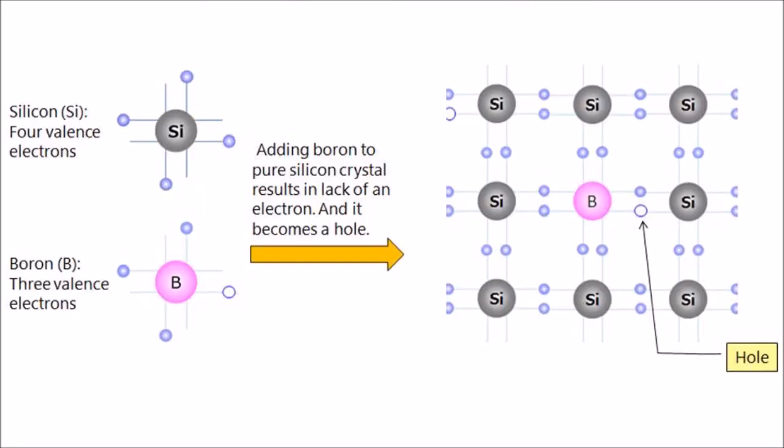In a p-type semiconductor, a large number of holes are created by the trivalent impurity, and when a potential difference is applied across this type of semiconductor, the holes available in the valence band are directed towards the negative terminal. As the current flow through the crystal is by holes, which are carriers of positive charge, this type of conduction is known as positive or p-type conductivity. In p-type conductivity, the valence electrons move from one covalent bond to another.